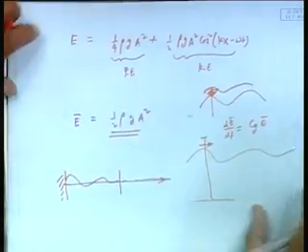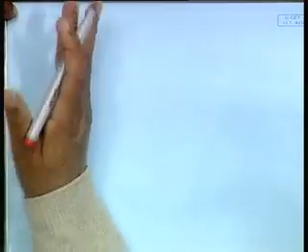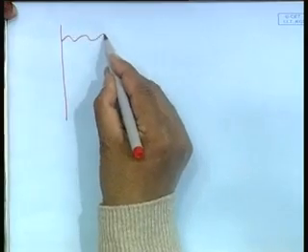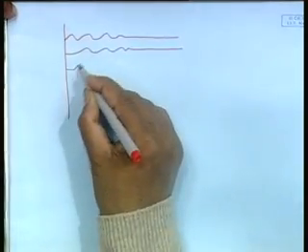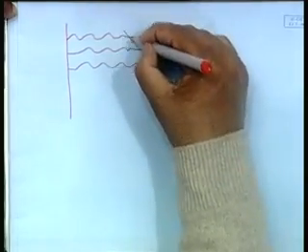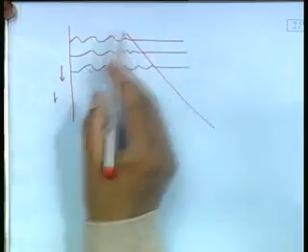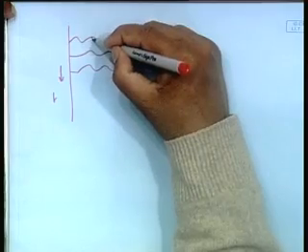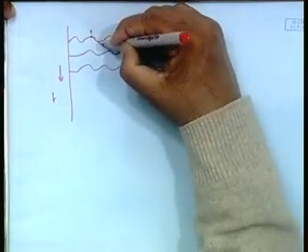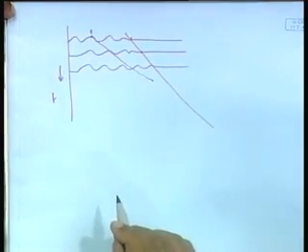This part is very interestingly seen this way. Supposing I turn on a wave maker at some point, at this time you will find the wave is like that, and the next instant the wave is like that. So, this front would have moved at some speed with time. This is the location of the front at some time, and the next instant, etc. But if I concentrate on any of the phases, the form, you will find that these actually move at twice the speed.